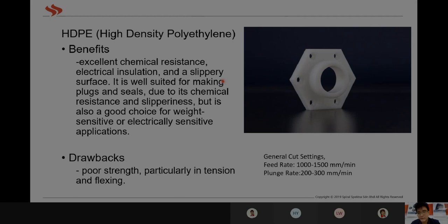In plastic, generally you want to use a ridiculously high feed rate and RPM, because if you focus your machining onto one point on the plastic, it will melt. If your spindle speed is too high at a certain point, or it's moving even by a little bit, it will melt as well. So you have to keep your settings high depending on the machine. In this case, I set it to 1000 to 1005, but again, it depends on your machine.